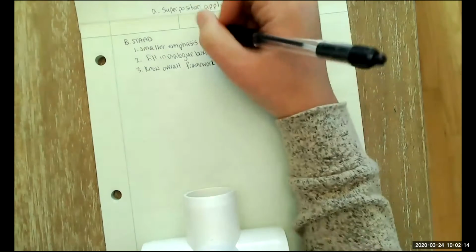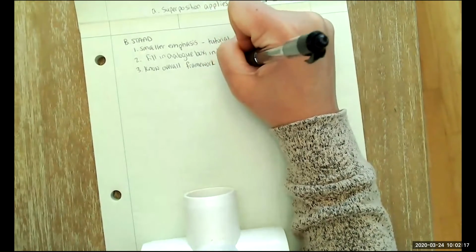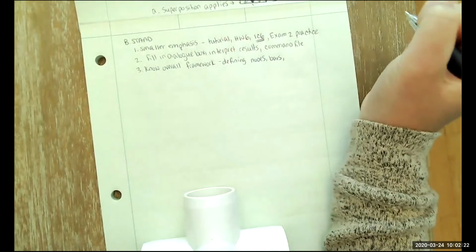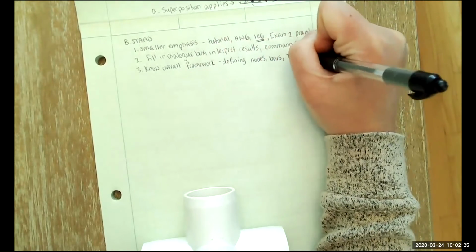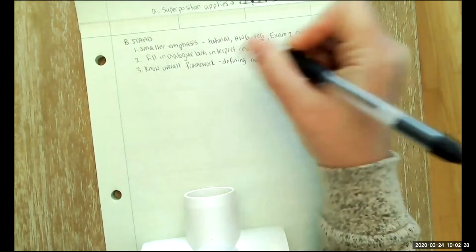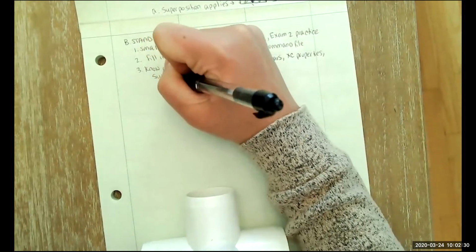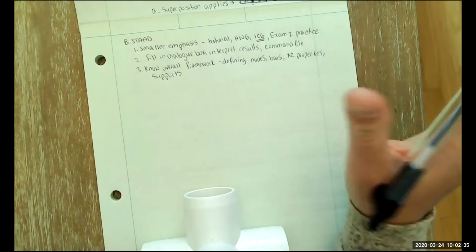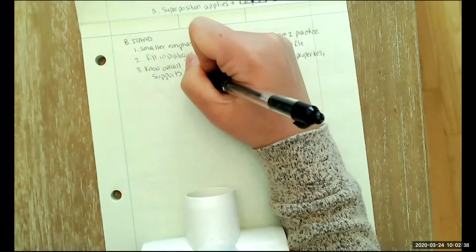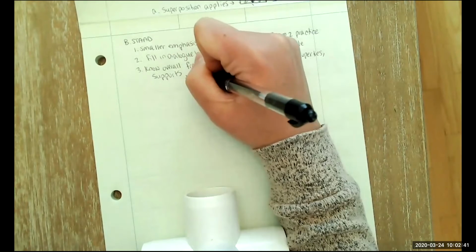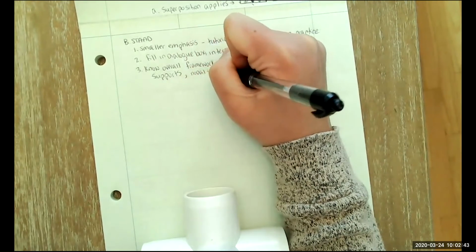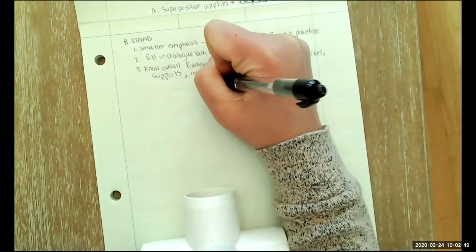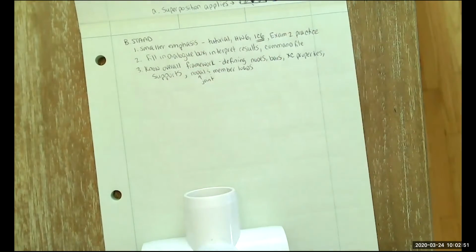So again, defining nodes, bars, cross-sectional properties, supports. Remember, we used a fixed but support to represent a roller. Fixed and pin are self-explanatory. Also, distributed loads. So we have nodal and member loads; STAAD calls these joint loads. And then again, interpreting the results.